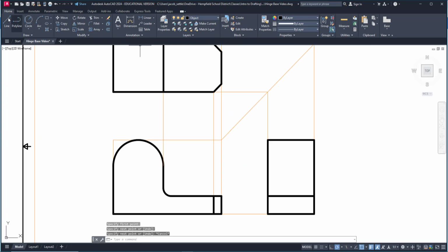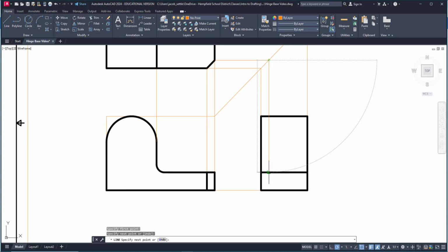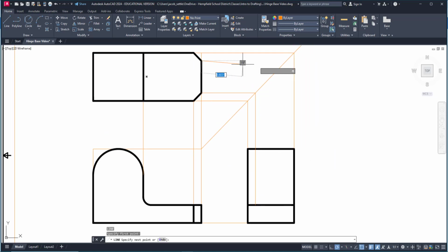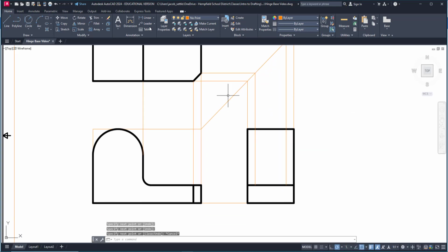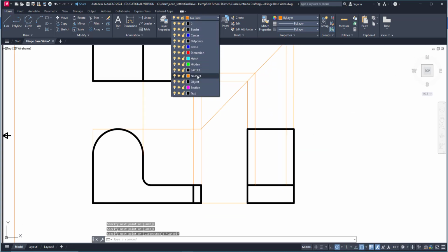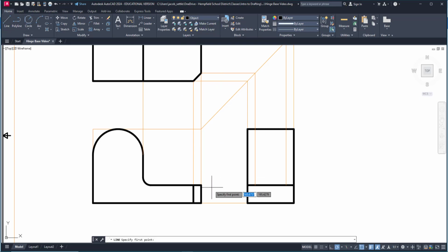You have the chamfer you'll need to project over to the right view as well. This is where you're going to use the 45-degree line. Make sure you're getting that intersection there, and then you can take that down. You have the same thing here. Take that over to the intersection and take it down. And then I'll switch back to object and go ahead and fill those in.